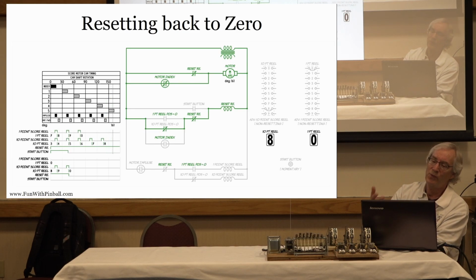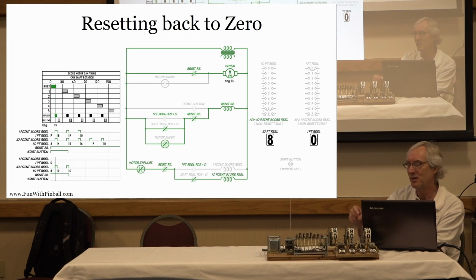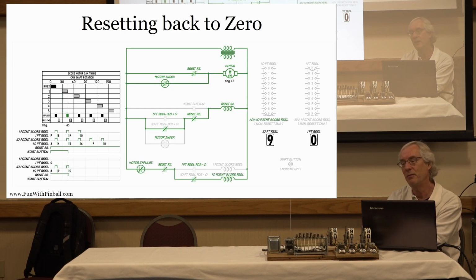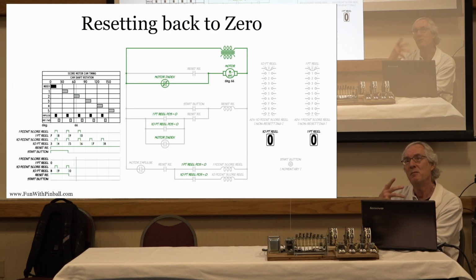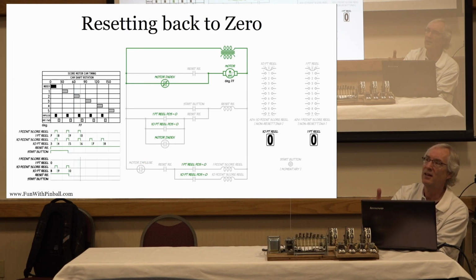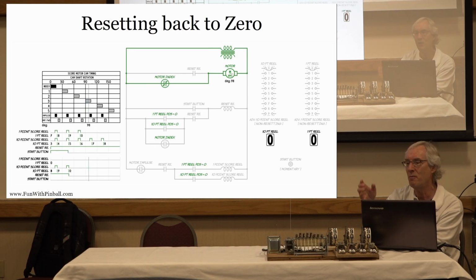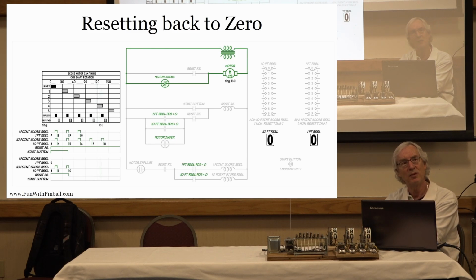Yeah, so when you have an issue when your score reel or your motor isn't behaving as it should, it helps tremendously to understand how it should work. And then try to imagine a scenario where it would, you know, maybe my score never carries over, right? Well, you might remember there's a switch in there that has to close to make that carryover happen, right? I know my score reels work independently, so the coils must be good, but there's something broken in the communication between the two of them.